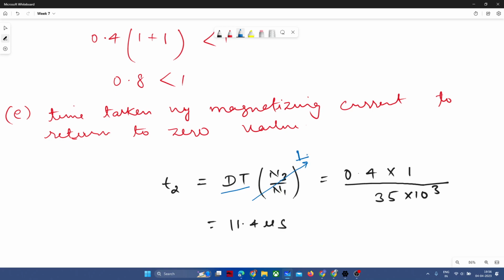In magnetics, are you going to discuss the magnetics for the DCM mode and CCM mode of the forward as well as the flyback? See, in the magnetics section, what I intend to discuss is the BH curve, inductance, permeance, reluctance, those kinds of things, Ampere's law and Lenz's law. Once you know how to design inductance from those parameters, you are free to include those values of inductance in these circuits, which we have already discussed for flyback and forward. So actually the magnetics part is a prequel to the isolated DC-DC converter.